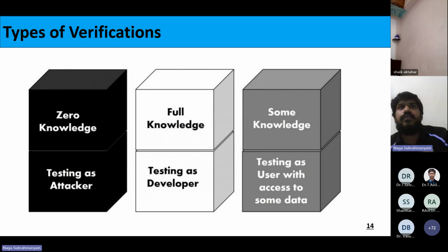You will develop an environment and produce the input data, put that input data on those input pins, and take the data, and try to understand the output according to their specification. They will give you the specification document describing what output it will produce for a particular input. They give the combinations, so that based on those combinations, you will write the comparison logic in your environment.